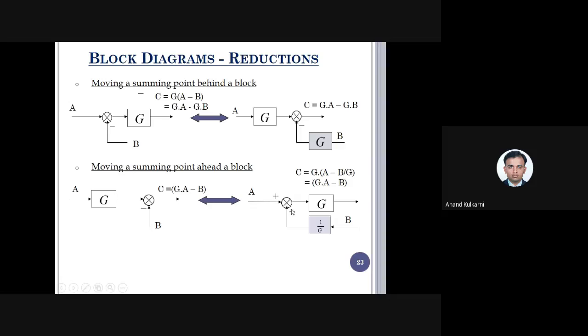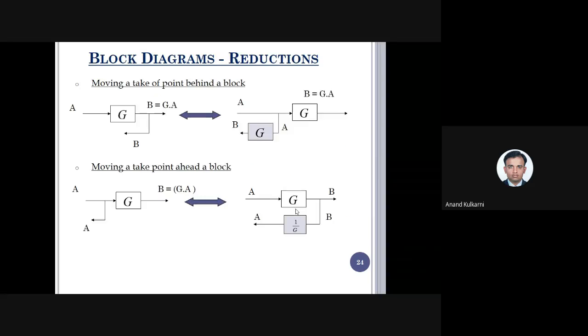But if it is shown, remember, in most conditions, only if it is a negative sign is the sign shown. If it is not shown, consider that the signal has a positive sign only. That is what you remember. Okay, sir, got it? It is important to remember this, because in the takeoff point, the condition is opposite. In the takeoff point, the condition is opposite.